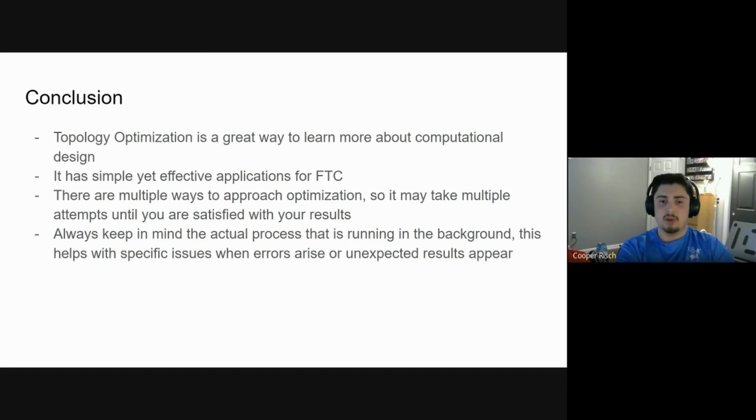And to actually track your progress, let's say you're getting rid of volume, track each step, see how well it holds up stress wise, see how much volume you took away, and see, as I get rid of volume, how is my model holding up? Because that's how you're going to track your progress if you want to really find the optimal solution. And again, that's just iteration. This takes process just like normal design.